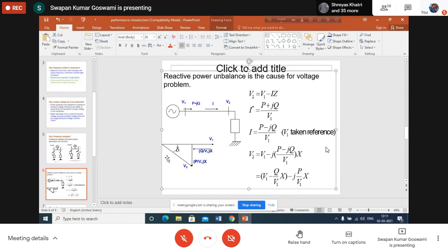The part that the capacitor used to do, it is still doing, okay, there is no change in it. That's why we are not taking that separately now. Okay, they have some effect, but that effect does not depend upon the increase or decrease in load. It does not depend much on the load. What depends on the load? The current flowing in the conductor depends on it. The series current, that means the current through the conductor, is dependent upon the load.